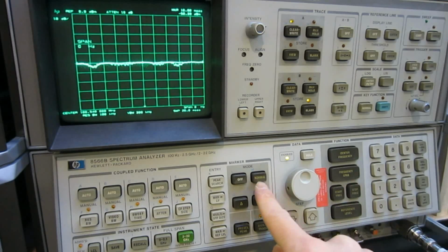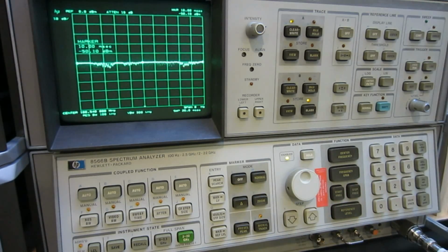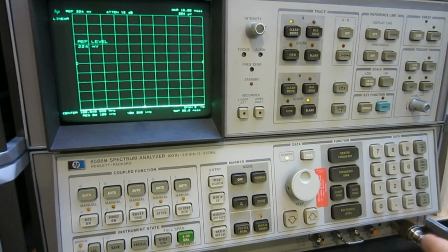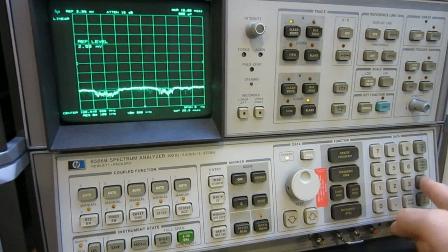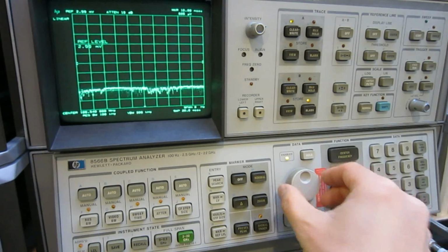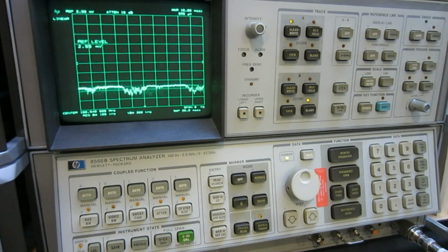We want to bring this peak to our center and set the frequency span to 0 hertz. So now, this is our signal that we'll be dealing with. And right now we first set it to linear and set the reference level to, let's say, 3 millivolts. And we have something there. I'm not sure if it's strong enough. Let's hook up the speaker and see what we get.